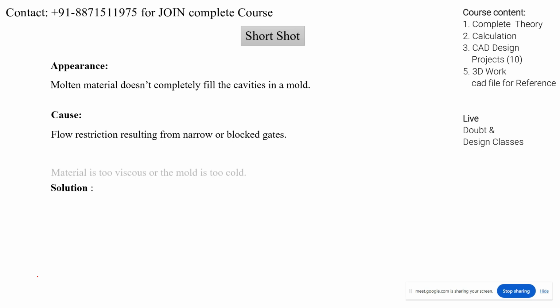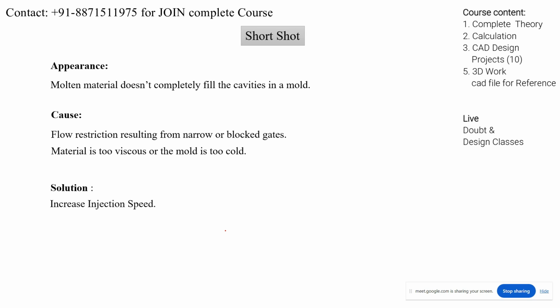And one more cause of a short problem is that the material is too viscous, or the mold is too cool. Solution: increase the injection speed, right? Or replace the material with lower viscosity. This is the main solution, right, if we have a short problem.